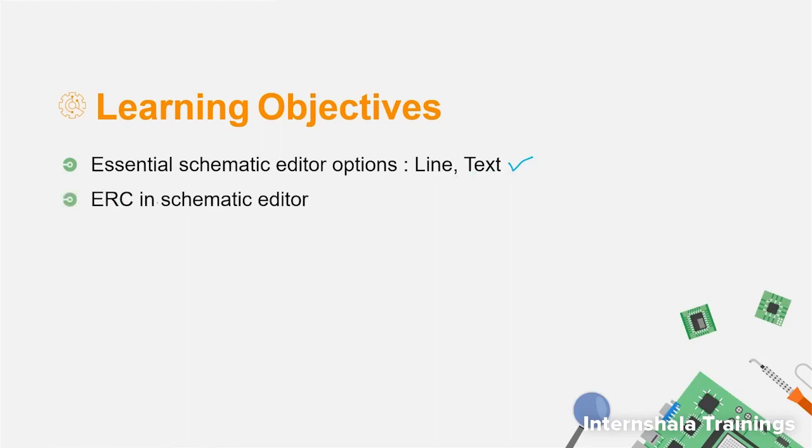After that I will give you a brief overview of the ERC tool, which stands for electrical rule check. Basically the ERC tool is very important and we use this tool every time we are done with the schematic design. So I will explain the purpose of this tool in this video. However, I'm not going to explain it in detail in this particular video. I have dedicated a separate video for this tool.